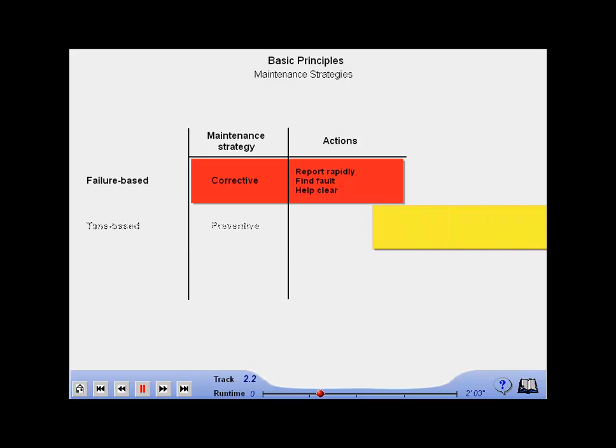The preventive case is based mainly on a time model. Here, using logistics tools based on time intervals, operating hour meters, etc., a warning is purposely triggered and servicing carried out reliably. The consequence here is that you might waste the service life of the unit replaced, because it might well have continued functioning a lot longer.